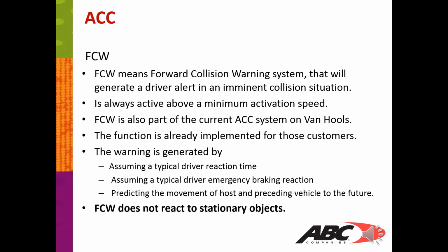The warning is generated by assuming a typical driver reaction time, assuming a typical driver emergency braking reaction, and predicting the movement of host and preceding vehicles into the future. FCW, or Forward Collision Warning, does not react to stationary vehicles.